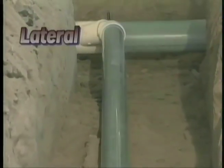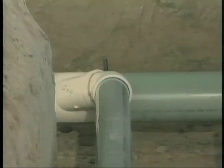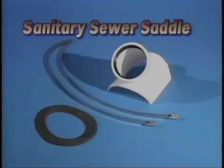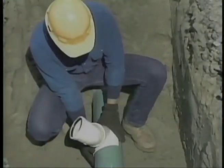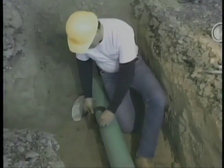A private residence usually has a smaller diameter service pipe, approximately 4 inches around, called a lateral, leading out to the sanitary main. The service pipe is attached to the main using a saddle that is either strapped with stainless steel clamps or is glued to the main. Sewer saddles are sometimes specified by the plumbing code to be set at different clock positions on the main line. Check the local code and project specifications for the proper clock position for all service installations.